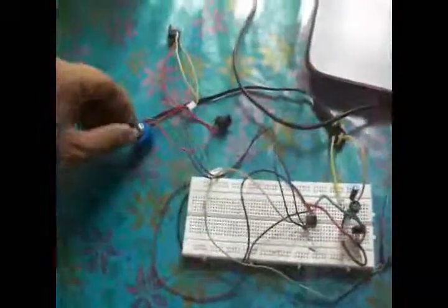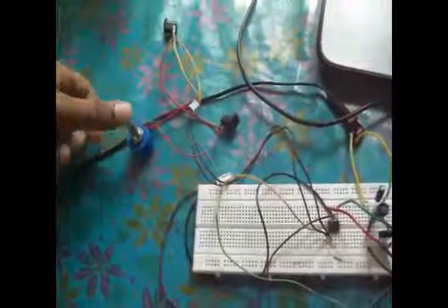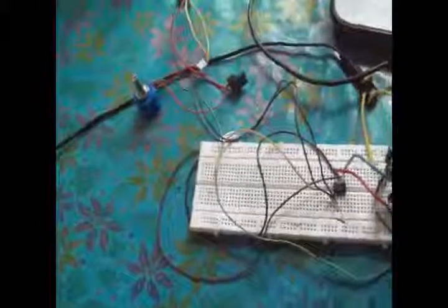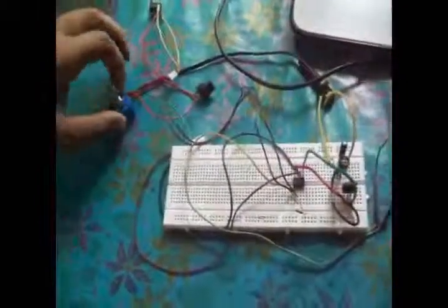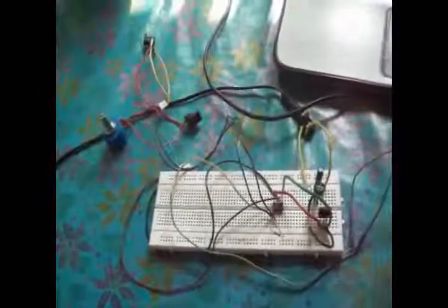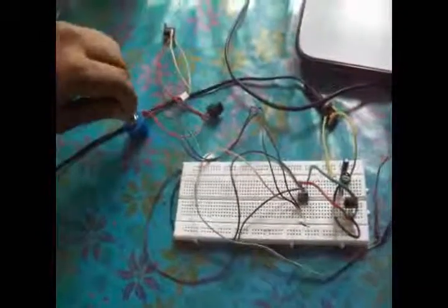Now the second one is the current, which is measured using a current sensing resistor. We used a potentiometer so that we can calibrate it, so that the multiplication or division factor to get the current from the voltage across this resistor will be 2 power n, where n is some integer. It could be 2 power minus n or 2 power plus n. So you can calibrate it using this.